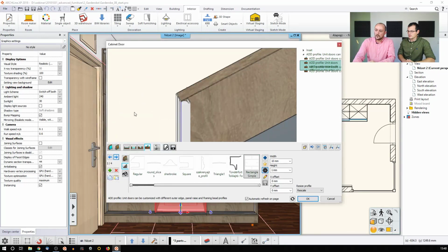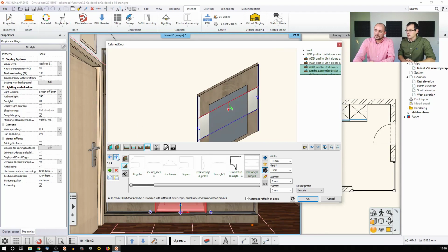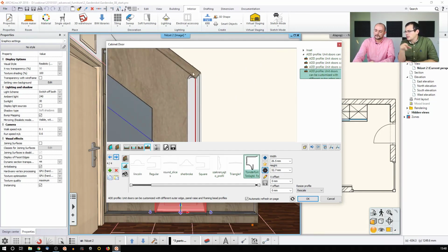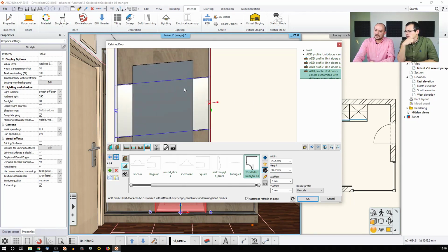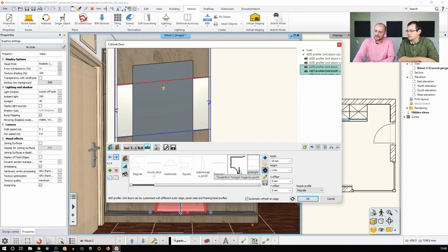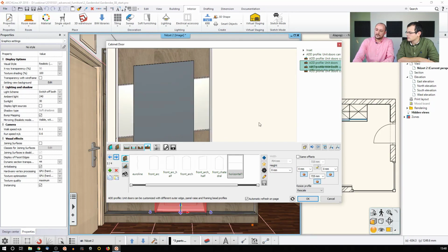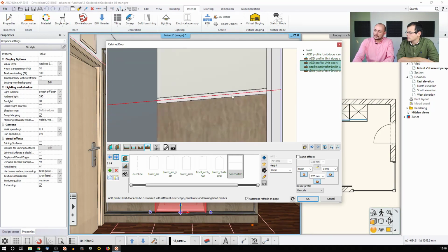And actually, there is the other one on the other side. Let me just quickly go there. That's the other one. It's just a mirror image. What about the vertical panels? The verticals here, you can either use this, or you can actually click on the bar itself, so the software will select it. And this is actually just a simple rectangular profile having a specific constraint from the top, and that is happening here as well, but it's repeated with the bottom, so it's constrained to the edge, and 725 from the bottom, and it looks like this.